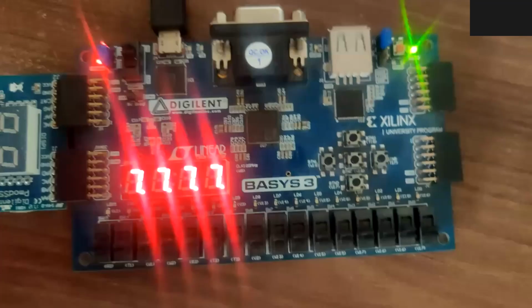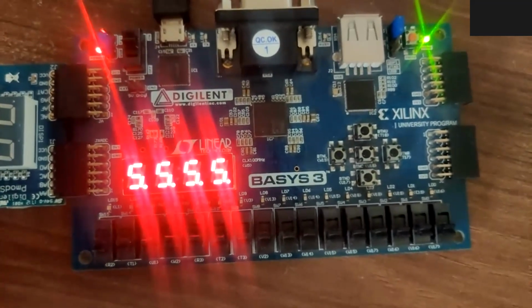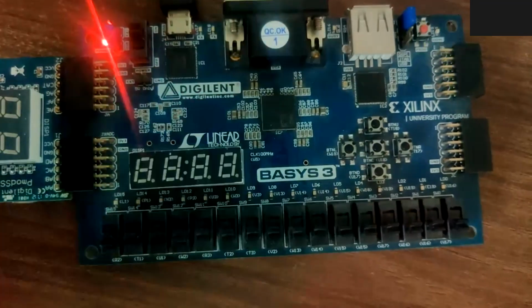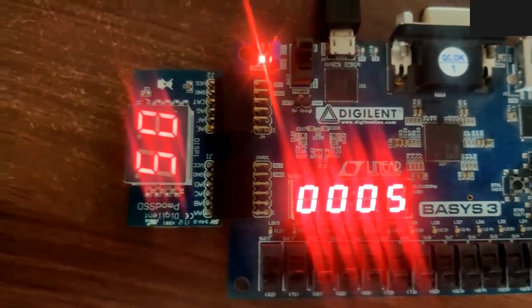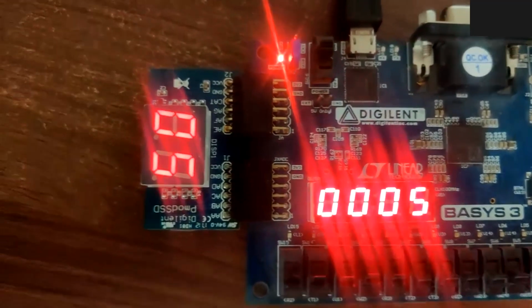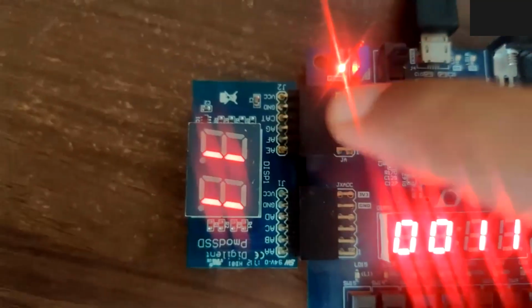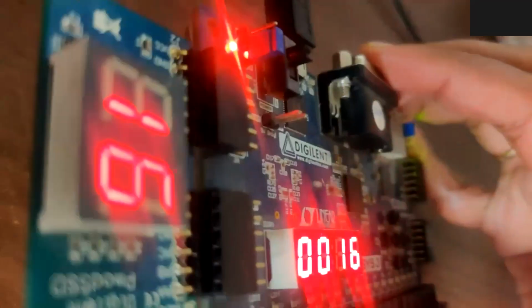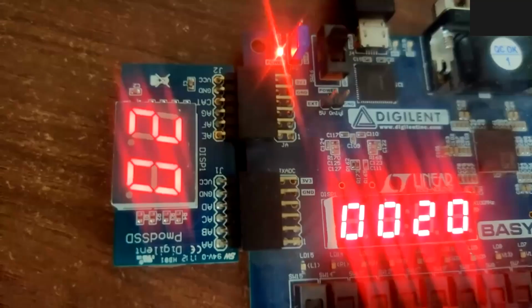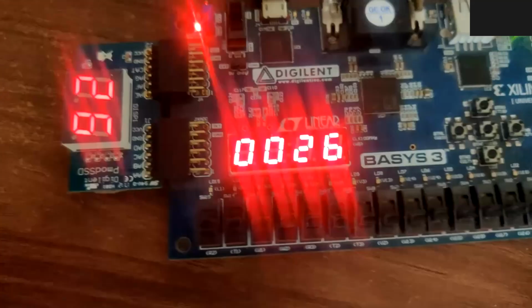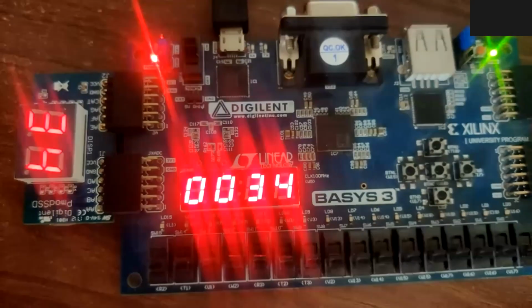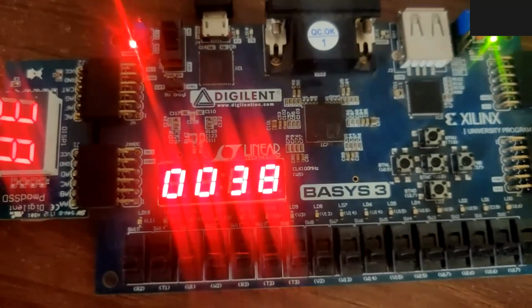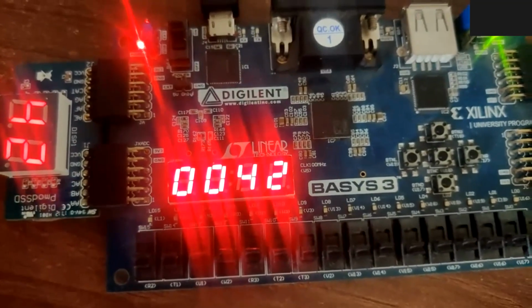Okay, so this is the default program. Now I'm going to program the FPGA board. The first thing you should look at is the PMOD 7-segment display. Here you can see that I have connected the 2 PMODs, and I'm connected to the lower pins of the PMOD. This is the PMOD A and PMOD XDC, and the seconds values are displayed on the PMOD as well as on the 7-segment display. Now the next thing you will see is that when my seconds counter reaches the value of 59, then my minutes counter will be incremented by 1.